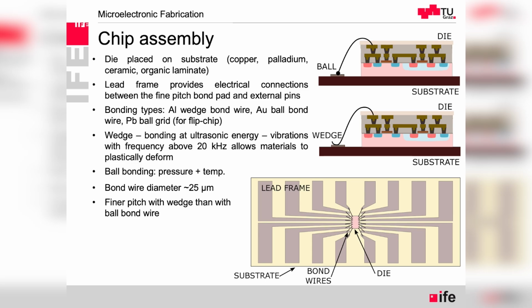So for these two types of bond wires, very often it's flexible to use one or another, but also we have to be careful which one is made of gold and which one is aluminum, to be compatible. We have to ask the assembly house what they do and what kind of bond the top metal layer on our chip should be, aluminum or gold, because there might be some incompatibility.